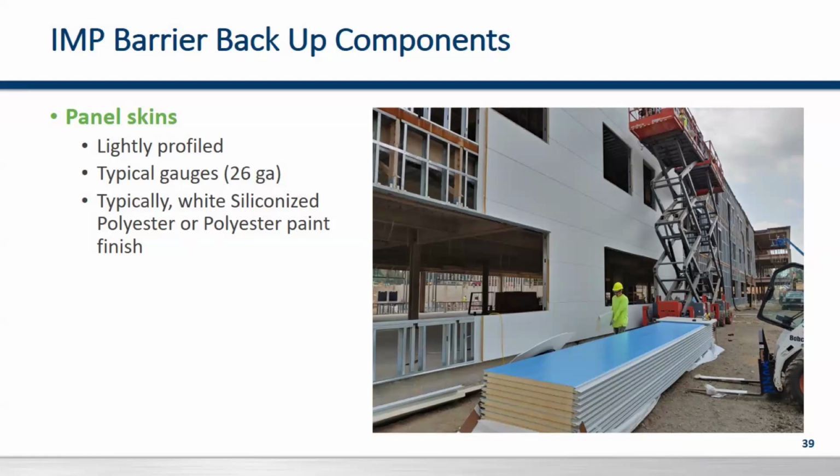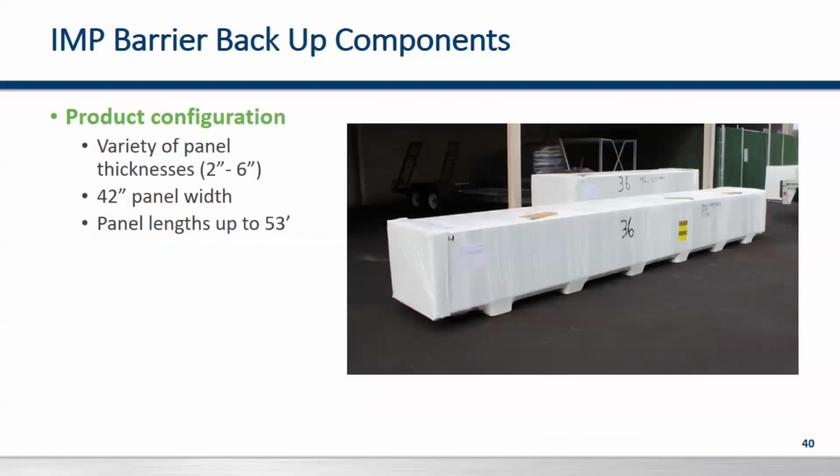So, if there was a construction delay, or say there was a retrofit and the single skin panels were going to be removed, this dried in wall assembly could stay exposed indefinitely. That's one of the huge benefits with the barrier backup systems.